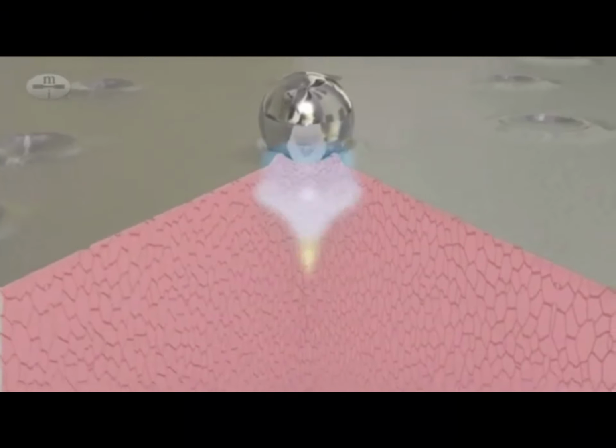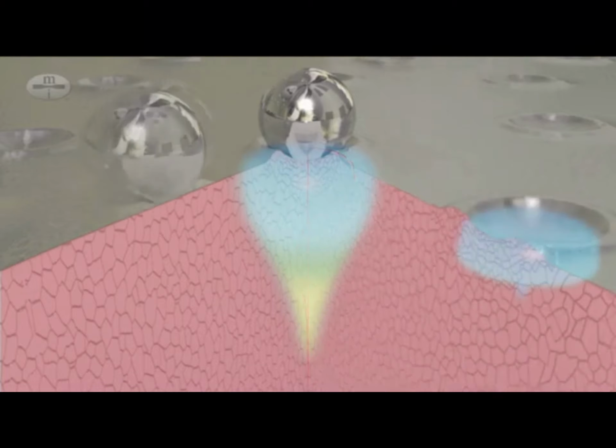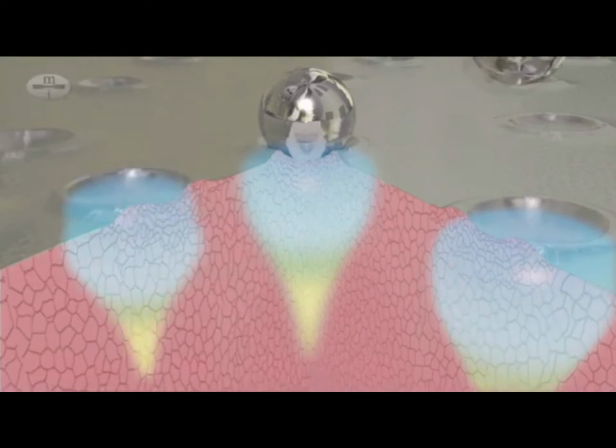The application locally yields the material, inducing beneficial residual compressive stress, the characteristics of which are dependent on the base material and component design. At the same time, unwanted tensile stresses are removed. The proven results from controlled shot peening show a dramatic beneficial effect on both the life and strength of components, welds and materials, making the material resistant to fatigue, fretting and stress corrosion cracking.